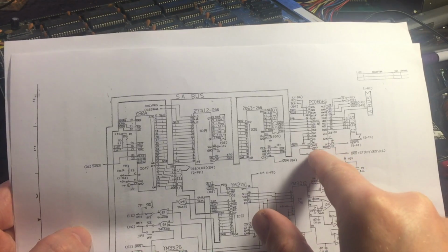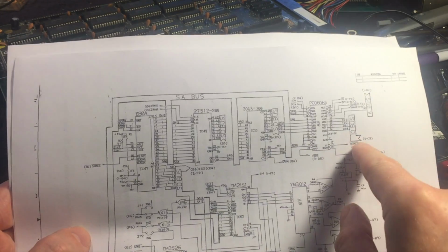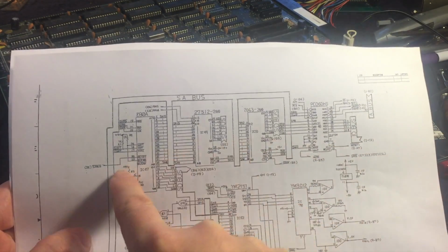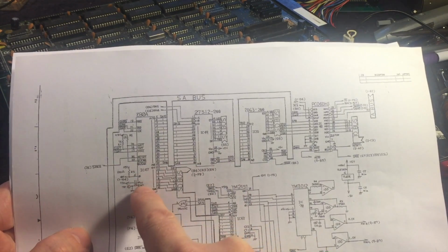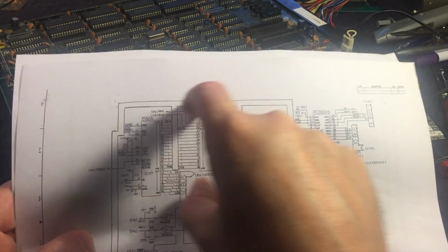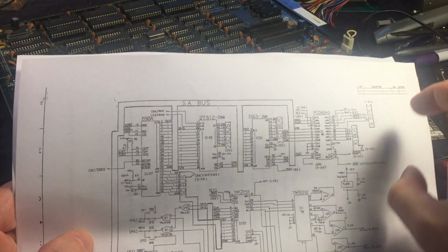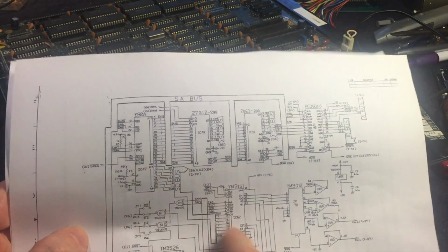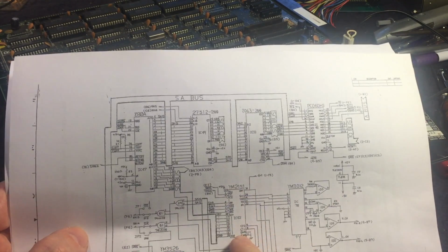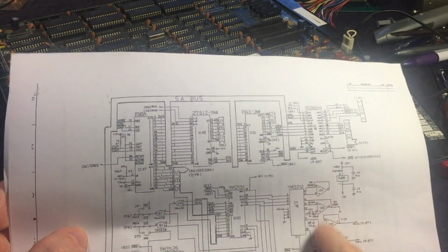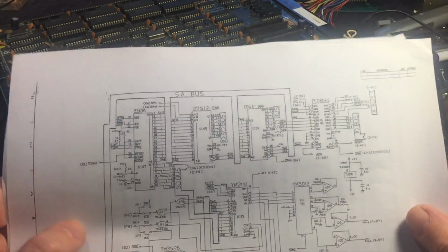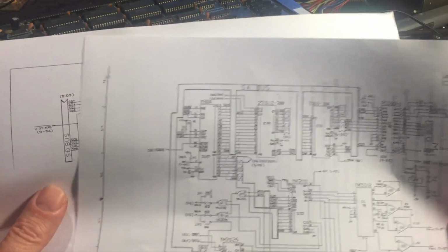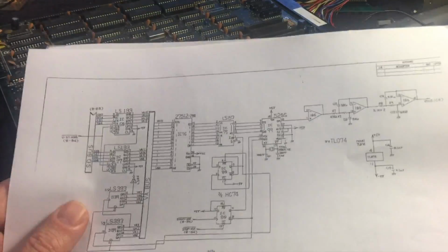Unfortunately, it's a custom chip that goes between the main processor bus and this Z80 that does the sound management. So that effectively right there is the separate computer that runs the sound section. And it plugs into a Yamaha FM synthesis chip, which plugs into a DAC, which plugs into some analog op amps for the output. And that takes care of the music and some of the sound effects.